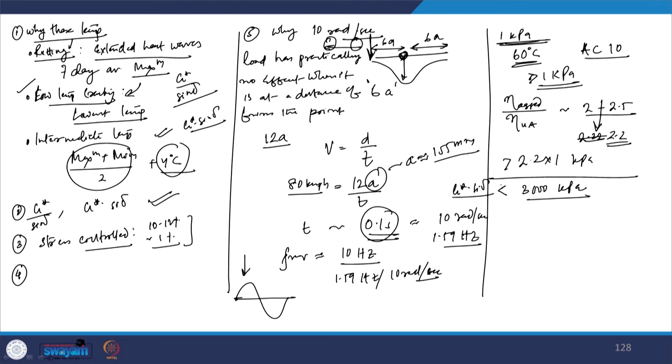When they gave this specification, many of the binders which were further tested failed to meet this conservative specification. Later on they looked at the value at which at least 85% of the samples should pass. They found that if the limit for G star dot sine delta is set to 5000 kPa, it should be satisfactory. So 5000 kPa was thus put as the specification.